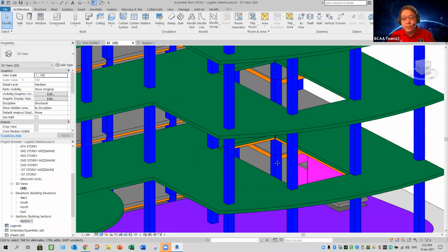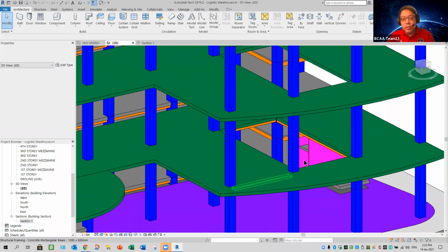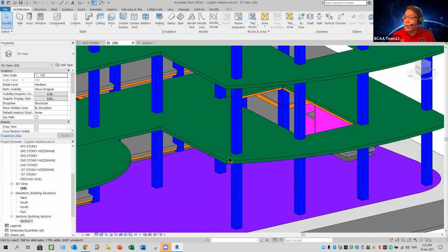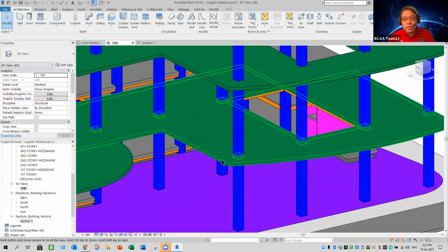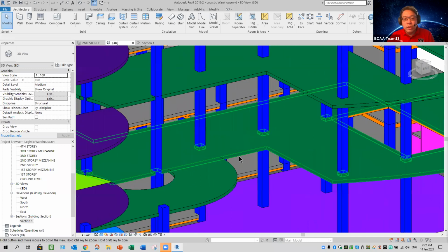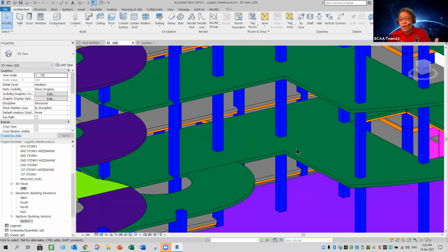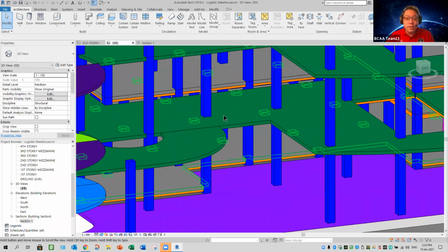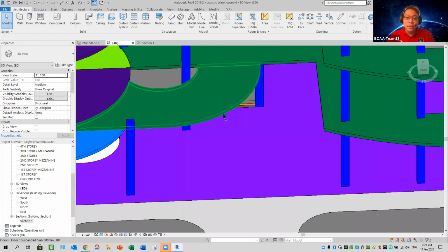So this is what we're going to do. Then here you may need to create a parapet wall. I said around 500 mm thick, but at least minimum should be 300, the parapet wall, and it should be around 1.1 meter high.